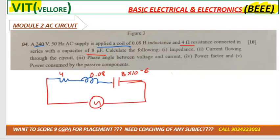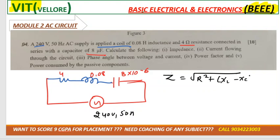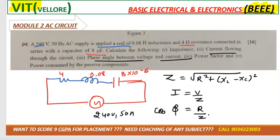Calculate the impedance. Voltage is given as 240 volt 50 hertz. Now you can get impedance, that is root of R squared plus (XL minus XC) whole square, right? Then you need to calculate current. Current is V over Z. Then you need to calculate phase angle. Phase angle is phi, means cos phi is R over Z. Then phi you can get in the similar way, cos inverse R by Z, right? Then they are asking the power factor. Power factor you already calculated, cos phi.